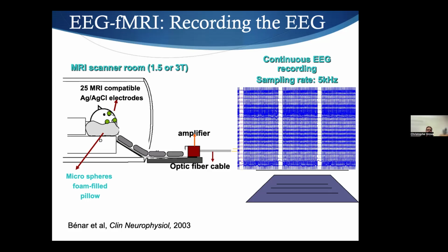So the machine to record the signal is outside, usually in the control room. You need to make sure you have very good synchronicity between your signal, and it has to be very rapid synchronicity, not one at 200 hertz. It has to be way faster than that. I'll go back to that. Typically, we are using a sampling rate of 1 kilohertz to 5 kilohertz.